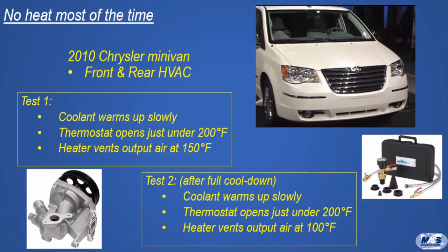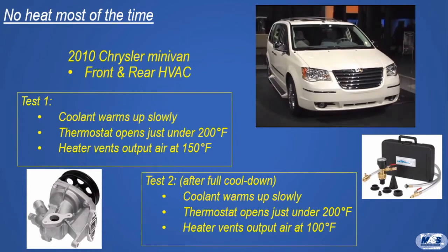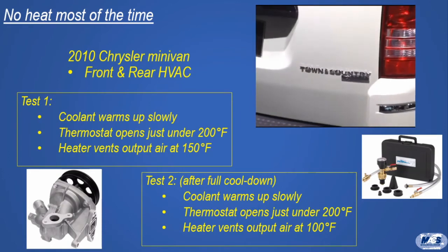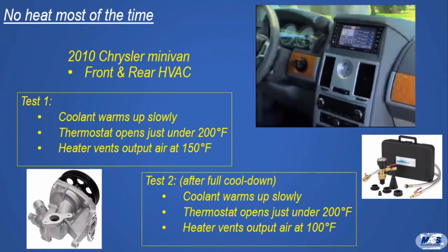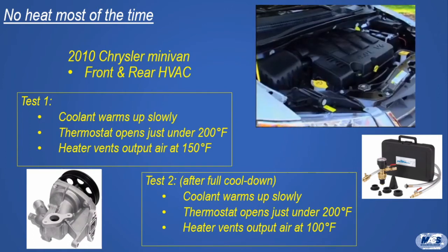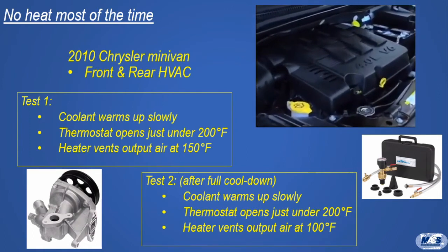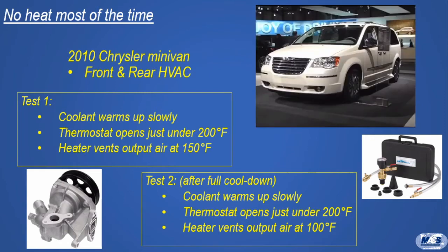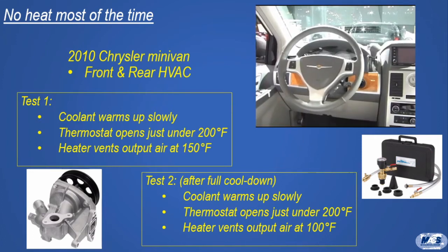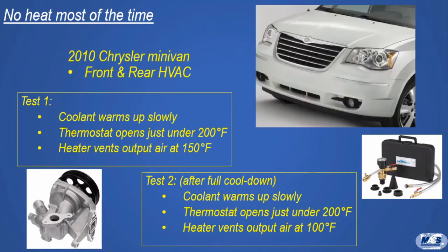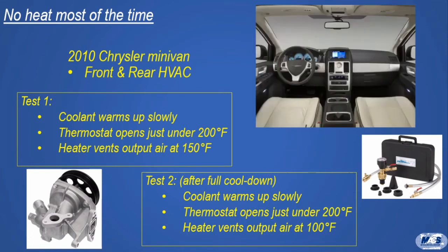No heat most of the time. The coolant on a 2010 Chrysler minivan, the Town & Country with both front and rear HVAC systems, warms up, although somewhat slowly. The thermostat opens at just under 200 degrees Fahrenheit, and the system will blow hot air, about 150 degrees Fahrenheit, from the heater ducts. But the next time the technician checks for heat, the outlets won't top 100.